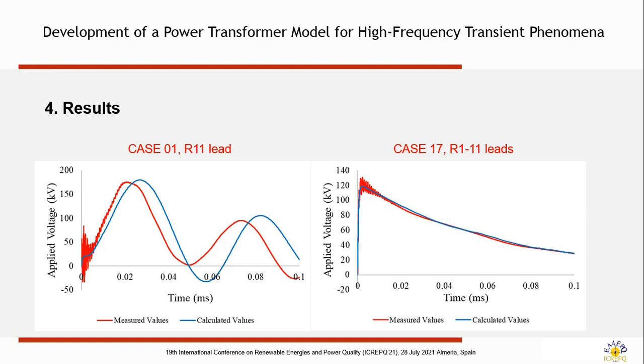You can improve the phase adjustment between the waves by modifying the value of the parallel resistance, that is the component which governs the decay and the damping of the wave. That resistance is a mathematical value multiplied by an empirical factor. So with more cases, you can try to calibrate this value.